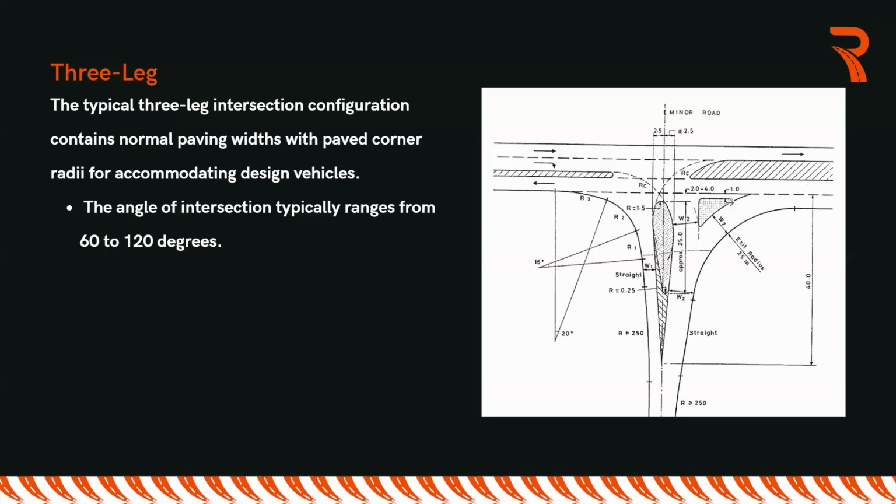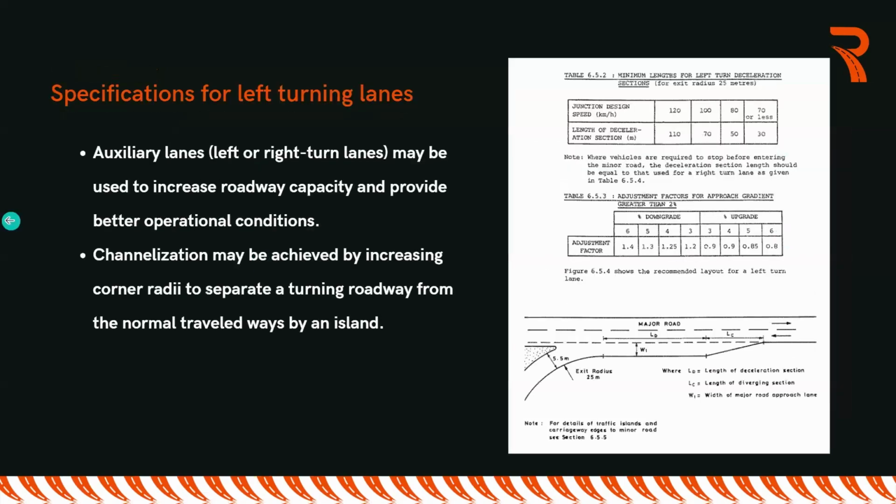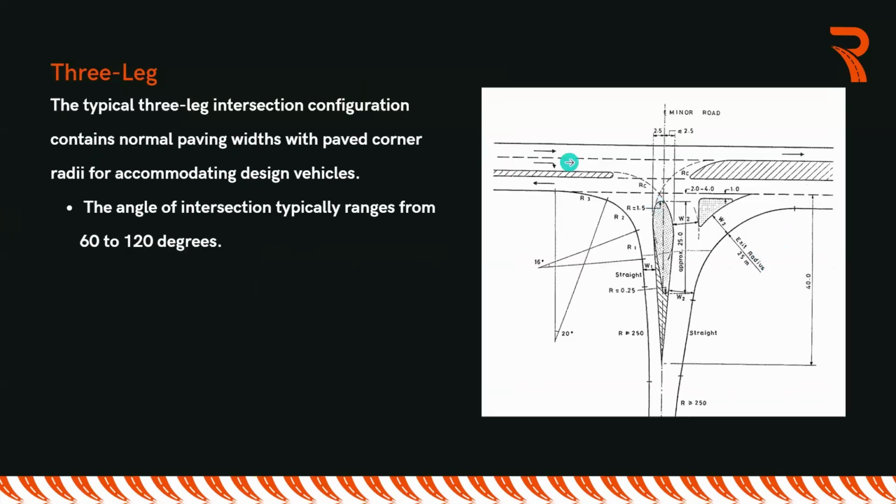Because ideally this means the intersection is going to control the alignment of the road at different scenarios. And that is when it comes to design perspective. When you're designing, you first figure out how my intersection will look. And then it is only from that you can continue and have the alignment of the entire section. So let us zoom in.